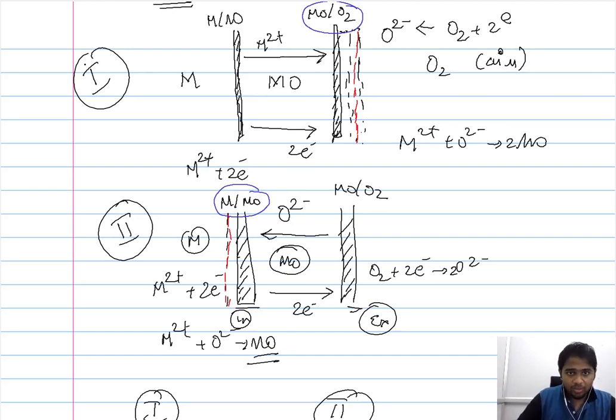Now the reason we want to distinguish these two mechanisms is because when the growth happens through mechanism 1, it is possible that the increase in the oxidation layer, because of its nature, can be removed. The newly added oxidation layer, because it is exposed to the rather corrosive environment, can be removed. Thereby, the thickness might remain the same, allowing a significant amount of M2 plus ions to pass through. What we essentially mean is that when the growth is in the external direction, the new layers that are being formed can be easily removed. So the thickness of the metal oxide might appear to be the same, but the consumption of the metal does not remain the same, or it doesn't mean that it has stopped.